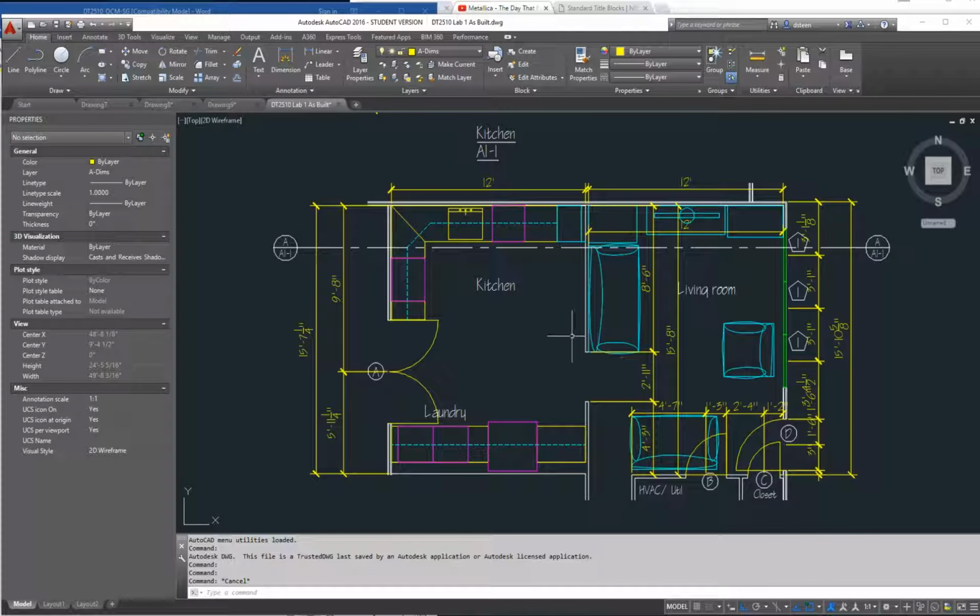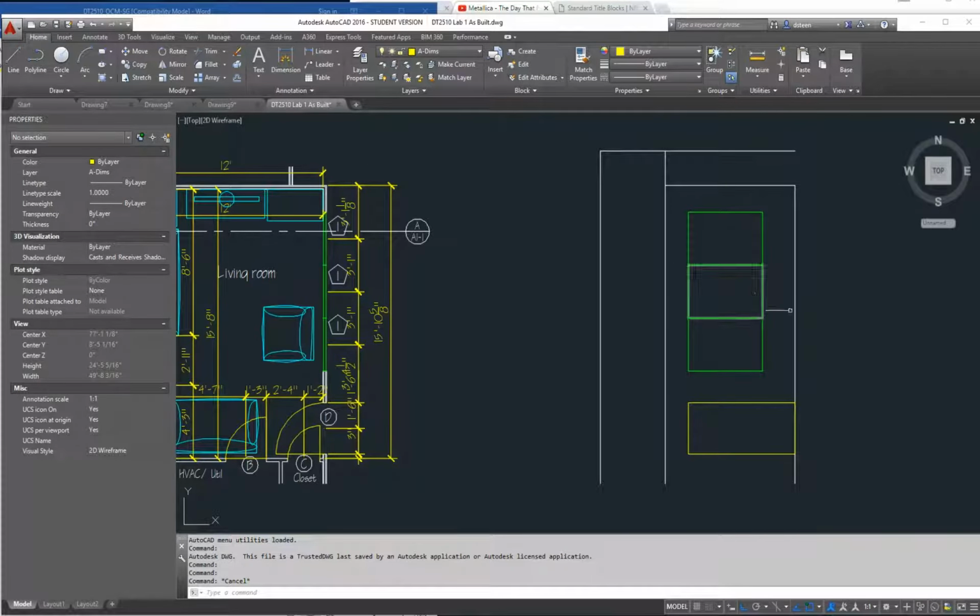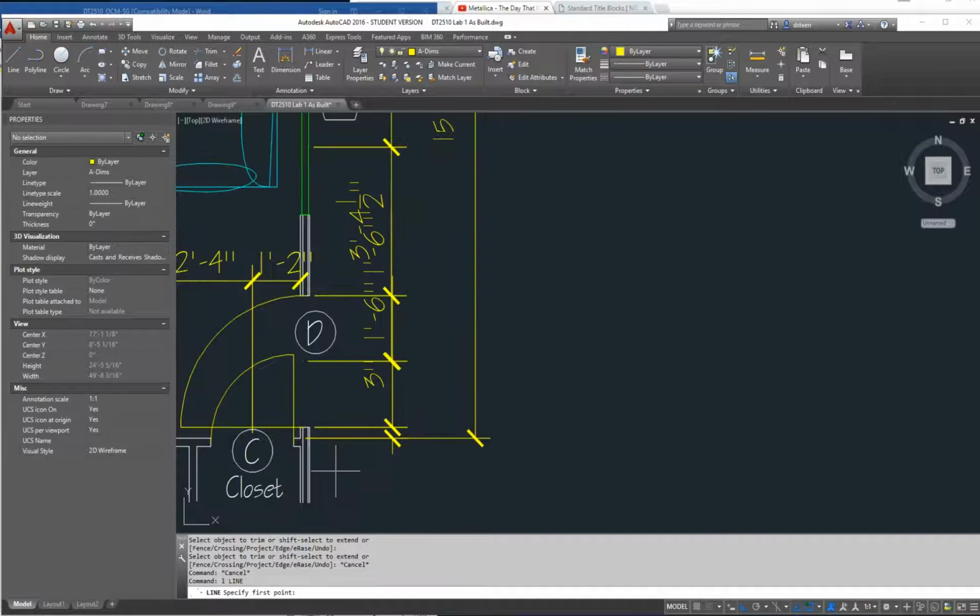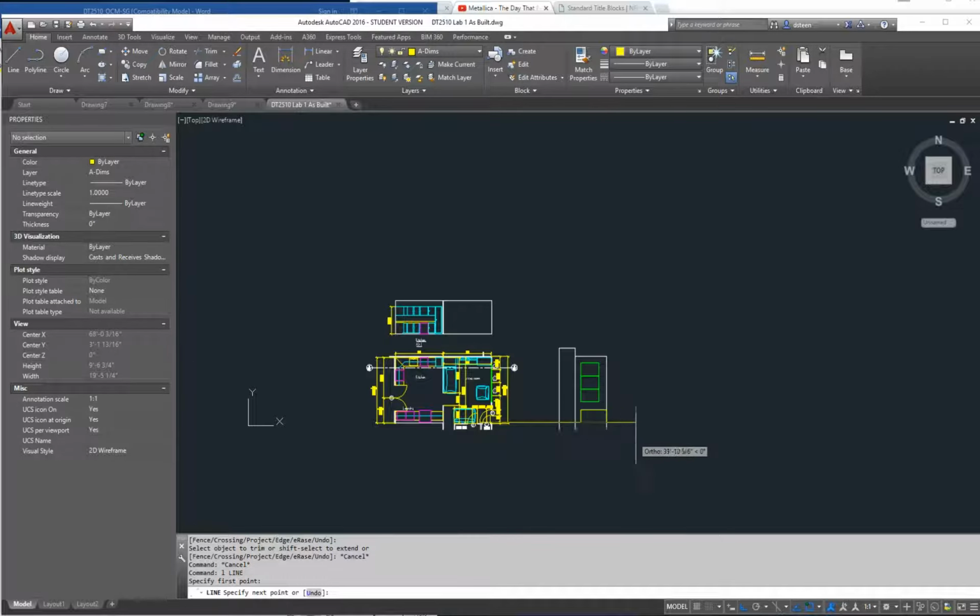This is what it takes to make your floor plan. So you're going to need this floor plan so that you can eventually make an elevation. Now here's a rough elevation, and I guess that shouldn't be there. Got my soffit and my roof here. My front windows, see I got 3 front windows here. I got my door. And you get that by projecting this information over.